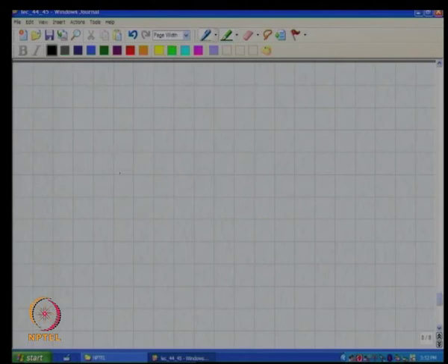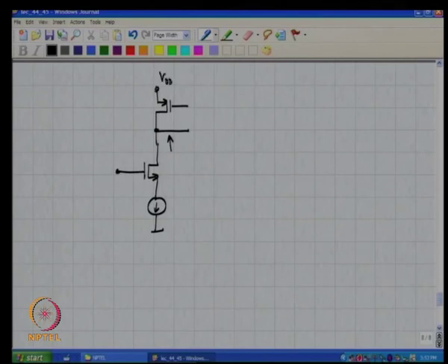I think one of you had suggested this when I was discussing the common mode half circuit. All of you are aware that instead of using an op amp, if this node potential is going up, we need to make this also go up. So, there is no need to use an amplifier in principle, one could actually connect these two. Okay. Now, if this is the common mode equivalent, how do you think the actual circuit will look like?